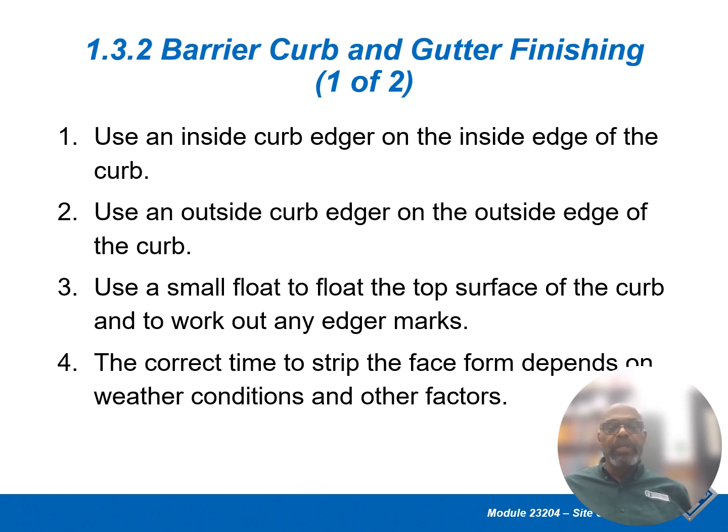So number 4, the correct time to strip the face of the form depends on the weather conditions and other factors. If it's very hot outside, or if it's cold outside, or if it's raining, many times you have to cover it. You need it to cure and give it time to cure. Many times, to slow down the curing process, they would keep some of the moisture in by covering it with plastic to keep the moisture from evaporating, especially when it's very warm outdoors. But the plastic can be used also if it's raining. So again, keeping humidity and time to cure concrete is everything. Temperature and time.